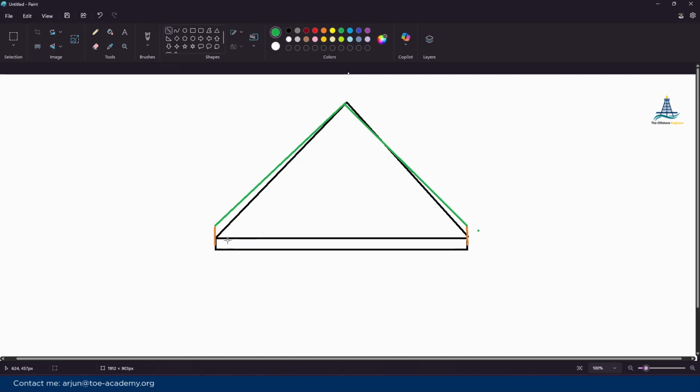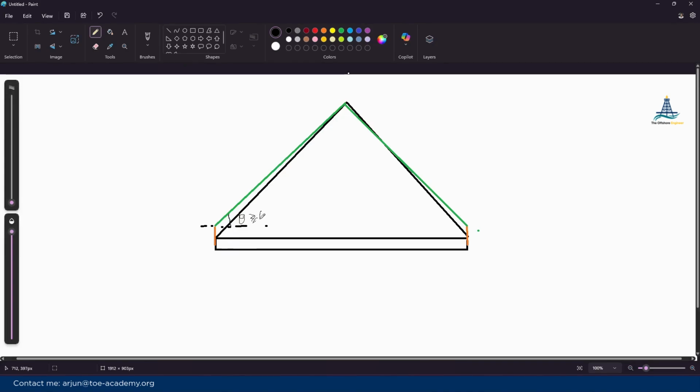When we come to the hook point, one thing we need to be very clear about is the angle this sling makes with the horizontal plane. This angle should be minimum 60 degrees, and we need to maintain that. So first I will create 2 members. One for the pad eye, which will be a dummy member, and another one for the sling.